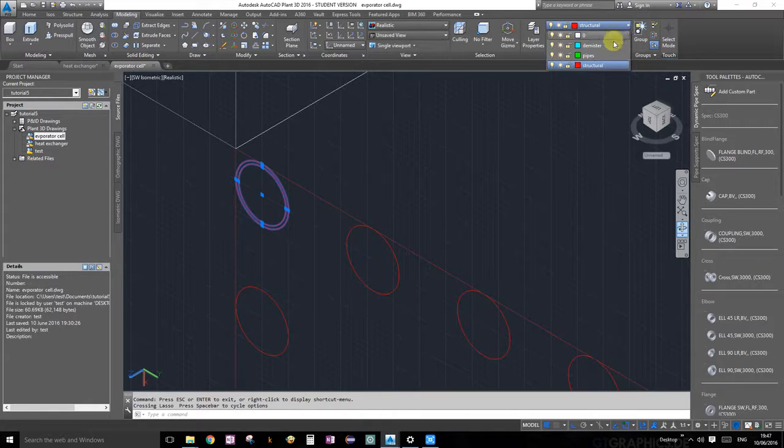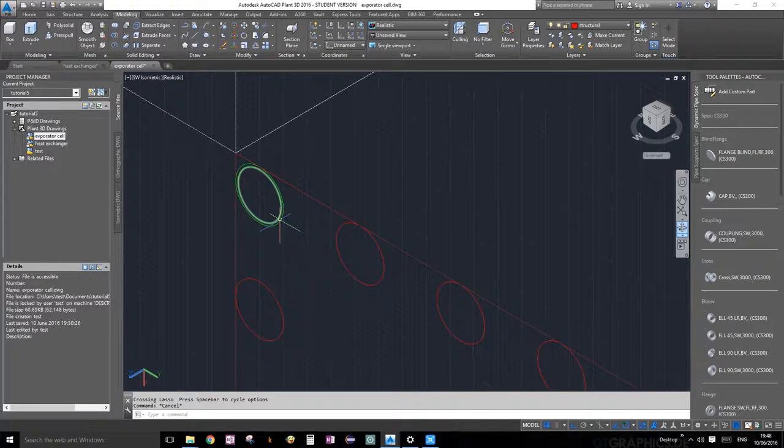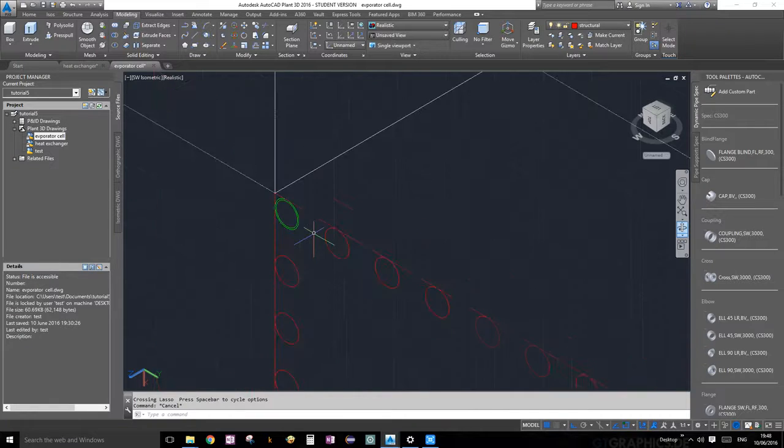So let's go ahead and select the objects and move it, and just from the drop down menu select the pipes. Your current layer is still structural, but once you select something and with the drop down menu go to a different layer, it moves the selected object to that layer. So as you can see, now we have our nice little thing on the piping one.